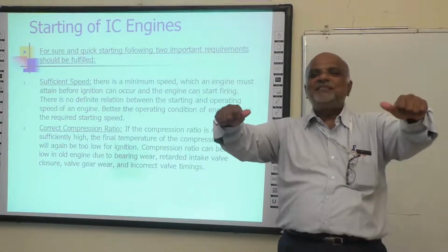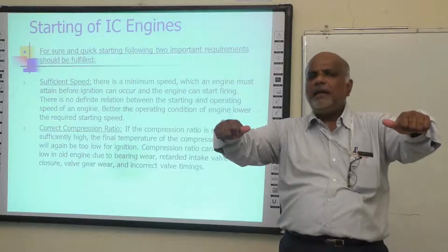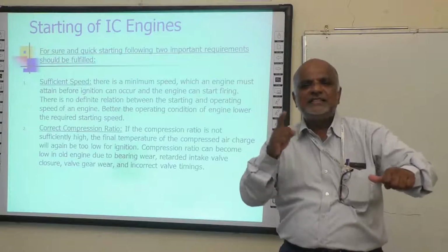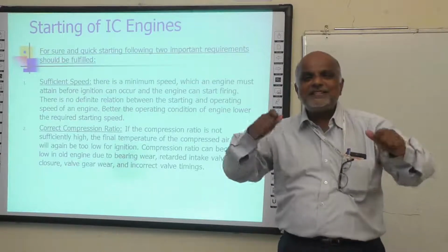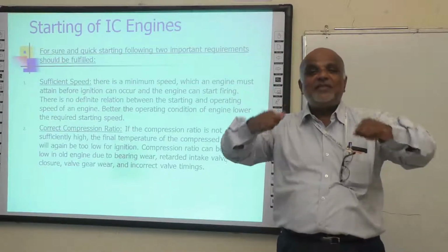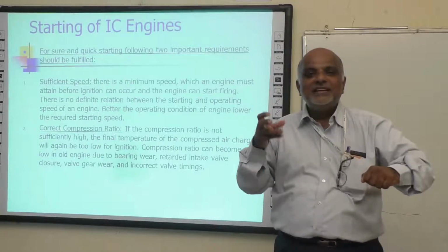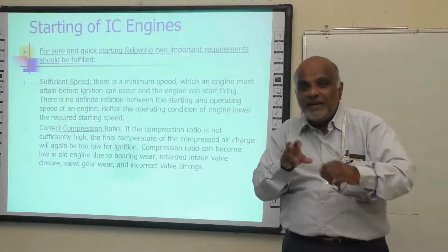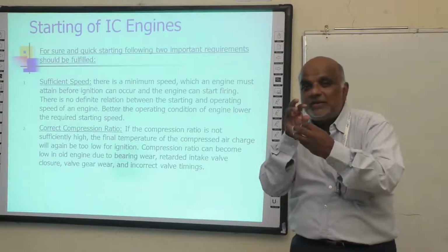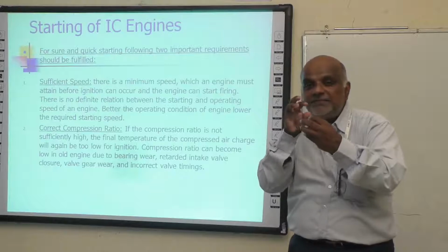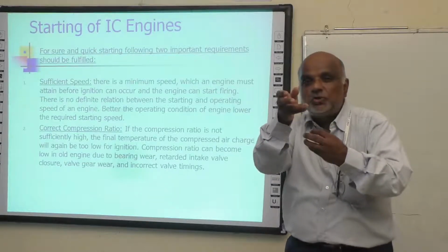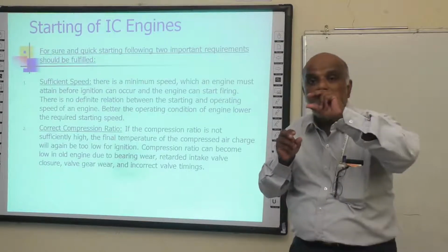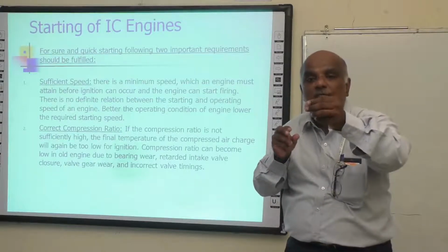And as you press the button, what's happening? Some sound is coming. When the sound comes, what is it? The electrical power from the battery is going to the self motor. It is charging the self motor, making the armature rotate, whereby there is a gear called the Bendix gear, which is spring loaded in the forward.